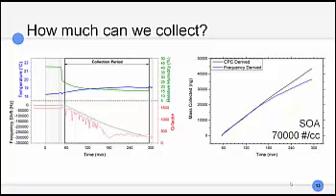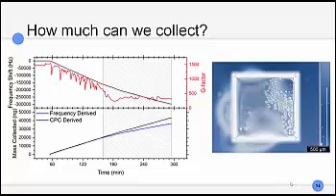So it's sort of implying that maybe after 100 minutes of collection that we are getting some deviation from the expected, and that might be the start of the saturation point. The expectation is that if we run this for even longer, the frequency shift should just level off and stop changing as any additional mass just isn't being registered by the resonator. But then you'll also notice that there is this essentially leveling off of the Q factor, and there's potential that those might be related. This really does require a bit more repetition, but they don't quite line up.